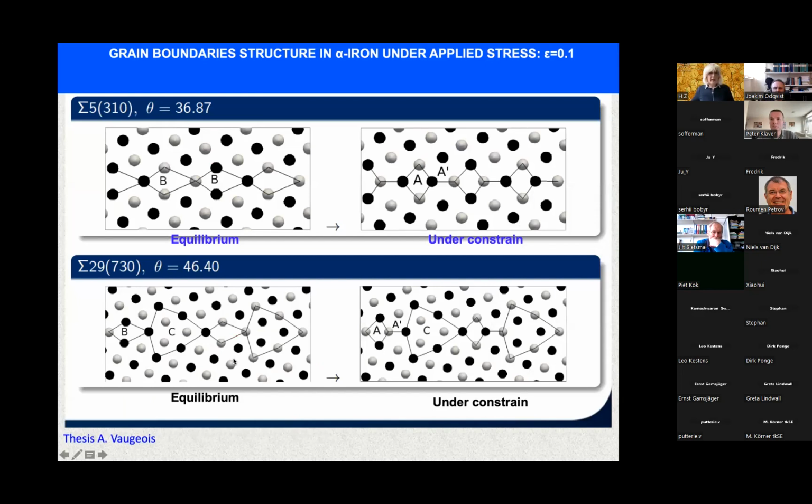If we are interested in the mechanical properties of materials, it's also useful to calculate what happens at atomic scale in some mechanical test. In this case, we have this simulation grid which can be adjusted with respect to the equilibrium position of the atoms or non-equilibrium position of the atoms, so we can change the distance between the atoms and introduce intrinsically the applied stress in the system.